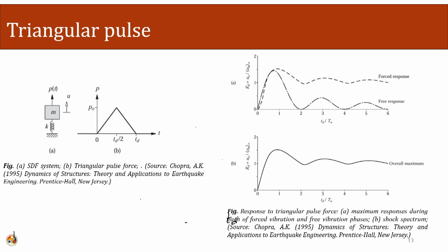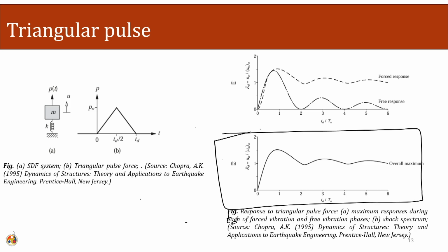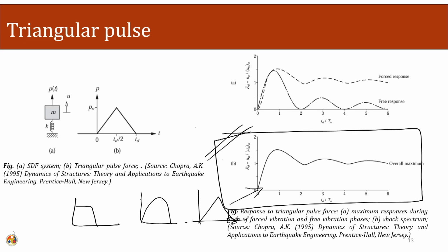Using all these approximations, we can directly calculate the response of a given system subjected to any type of loading. We have dealt with pulse loading and half sine loading, and right now we are showing the triangular loading. This is the response curve that can be directly used.